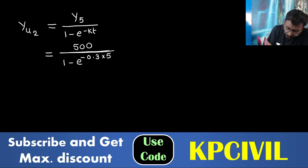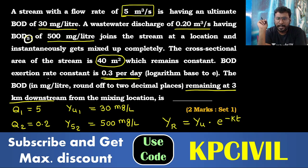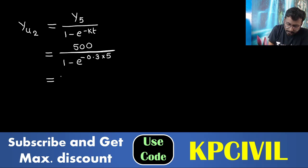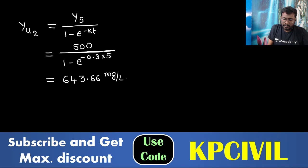K is clearly provided, 0.3 per day. So we are estimating the ultimate BOD, a simple conversion of 5-day to ultimate. Ultimate value, how much are you getting? 643.66 mg per liter.